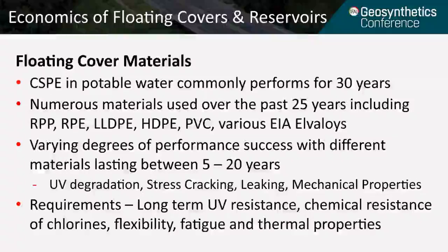CSPE, or chlorosulfonated polyethylene, is recognized as the leading material for floating covers in municipal water applications. CSPE in potable water commonly performs for over 30 years. There have been numerous materials introduced and used over the past 25 years for floating covers, including reinforced polypropylene, reinforced polyethylene, linear low-density polyethylenes, HDPE, PVC, and various EIA alloys. Our company has experience supplying and installing most of these materials.